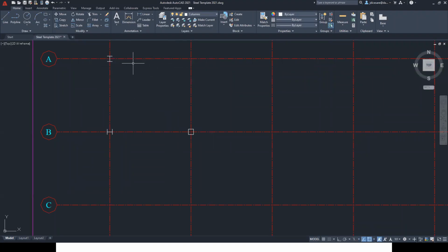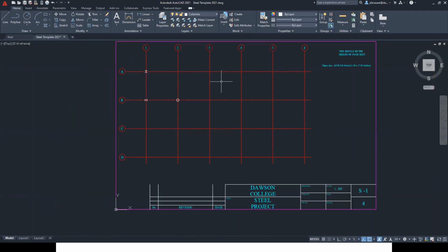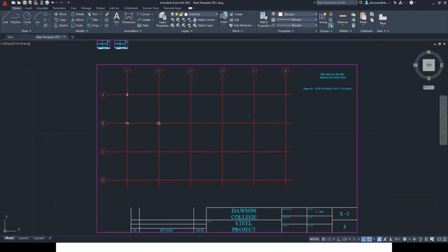Remember, the lines are not supposed to touch in structural steel. So look at the other drawing. If I see lines that touch, you're going to lose a lot of marks, because in structural steel, when things are pin connected, in other words, simply supported, you have to show that they're not touching each other. That's how it's represented. So this is your drawing to do your roof plan.